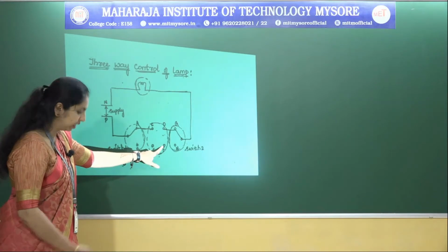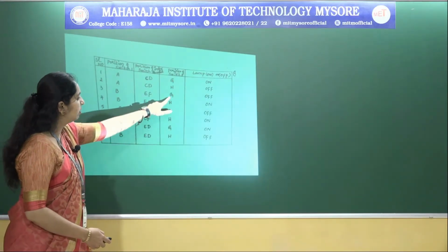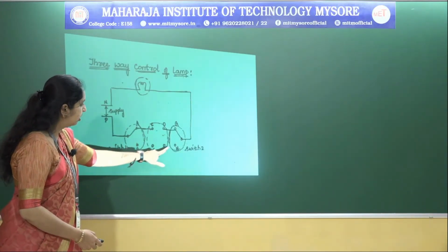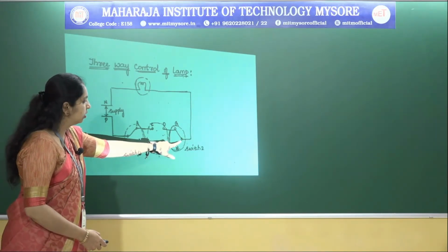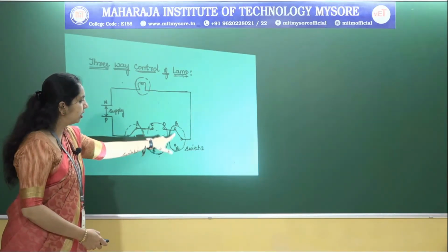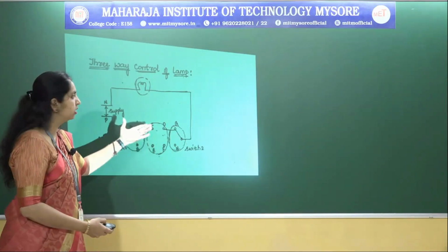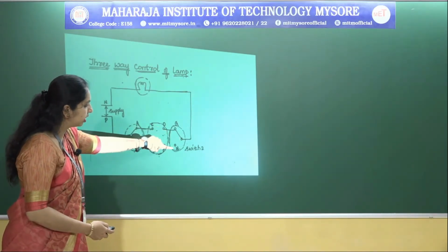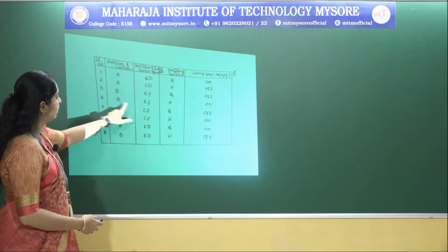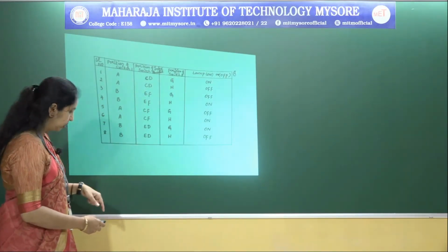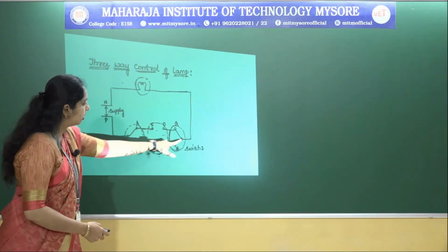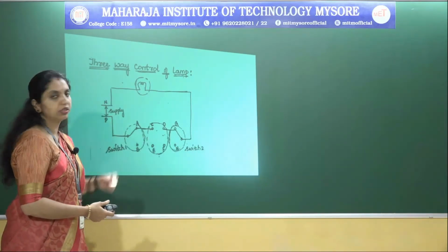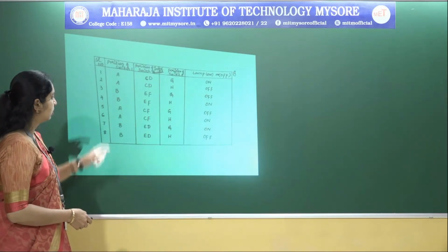Till this point it becomes a straight connection, and now we have the second switch at position G. So now we have a straight connection, but this is at G point. When this is at G point, of course there will be a discontinuity in the circuit, so it becomes off. That means the lamp does not glow. Instead of G, if we have the connection at H, what happens? That is what we have in the fourth condition. So we have B, E, F and then H. It becomes a closed circuit, and of course the lamp glows. So that is the fourth condition.